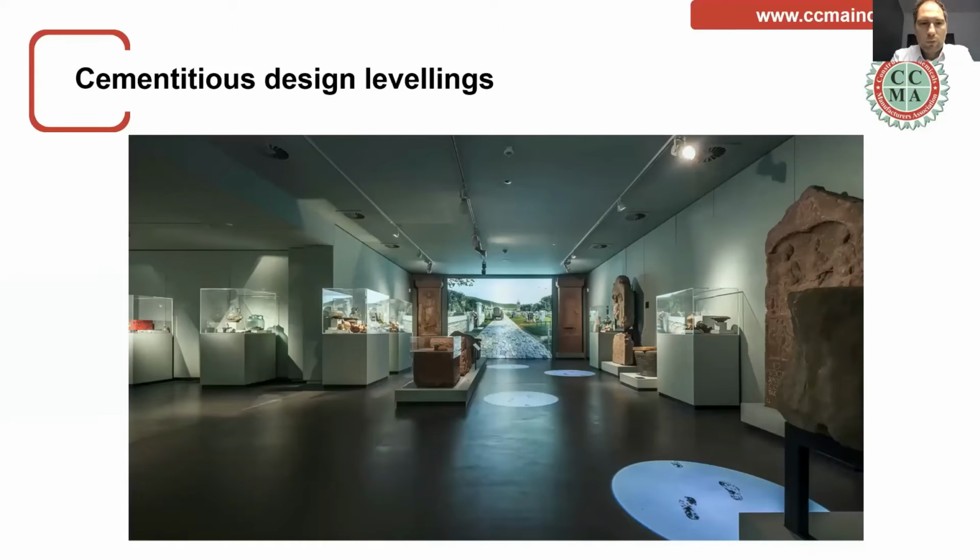Here's one project we did in the past and we are very proud of. This is a kind of museum, and for that case I'm showing you those thin layer screedings are very robust. They are very shock absorbing, and there are no issues of getting damages like deep scratches or maybe holes or pinholes in it, because the material hasn't that thickness like the self-leveling between 5 and 10 millimeters.